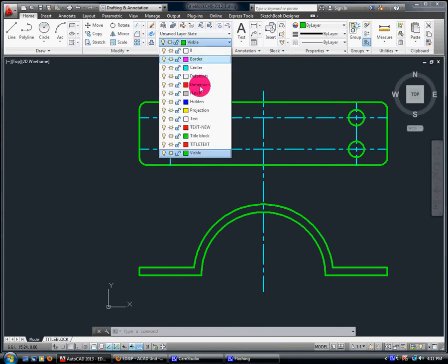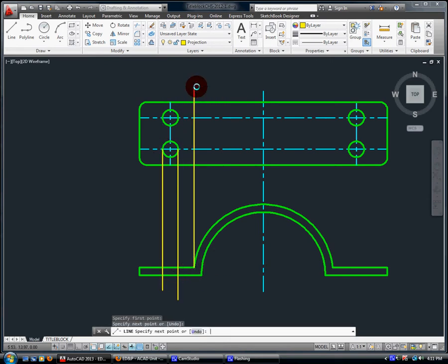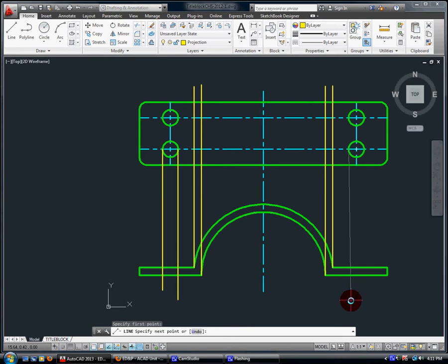So just like we were drawing by hand, I turn projection line on. And all I'm going to do is project those lines down, just like if I was drawing by hand. Remember, the rule is always project your lines up to wherever they match, then go back, draw the correct line. So think of this as your projection line, always drawn lightly, always project straight down. It can always go outside, that doesn't matter. The point is it lined up.